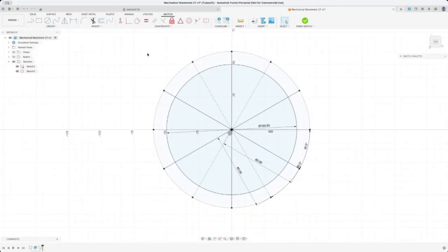With the center lines in place, we will then be able to create the spaces on the main body. We do this by offsetting the guidelines to create an intersection on the sketch. We will then cut out the intersection from the main body and repeat the pattern on a circular axis.